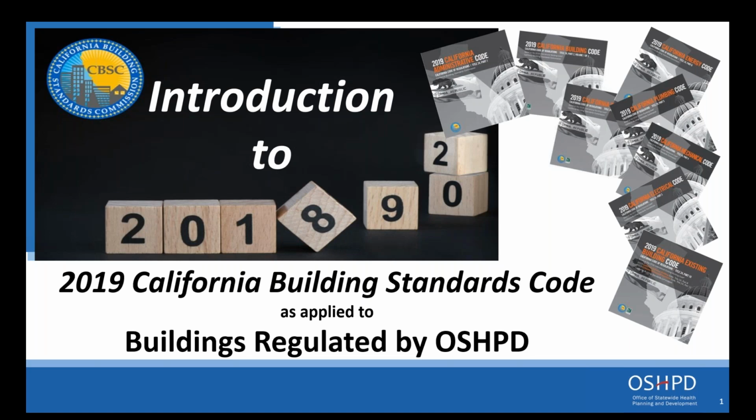Next question reads, if I repurpose an SPC 1 or 2 hospital building, will it then have to meet current Title 24 energy code? That's a good question. There is ongoing discussion on that. As of now, I would say, again, you would have to meet the remodel requirements or the alteration requirements of the energy code for that new project. But we are looking at that as well.